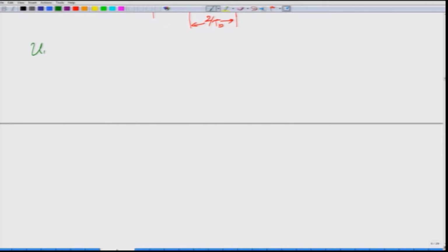Okay. Let us look at one more format, which is the unipolar format. In the unipolar NRZ, I am not going to derive the power spectral density in this particular case. Remember, for the unipolar format, symbol 1 is a pulse of +1 amplitude, and symbol 0 is 0. You are not sending anything over here, and the polarity of this pulse is always single. That is why it is a unipolar format.